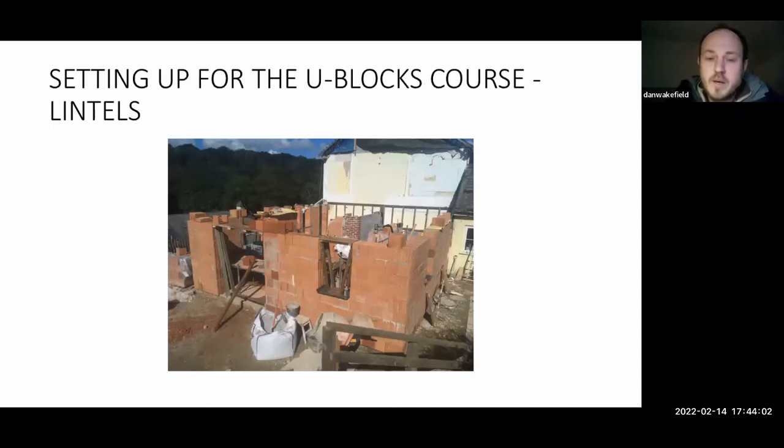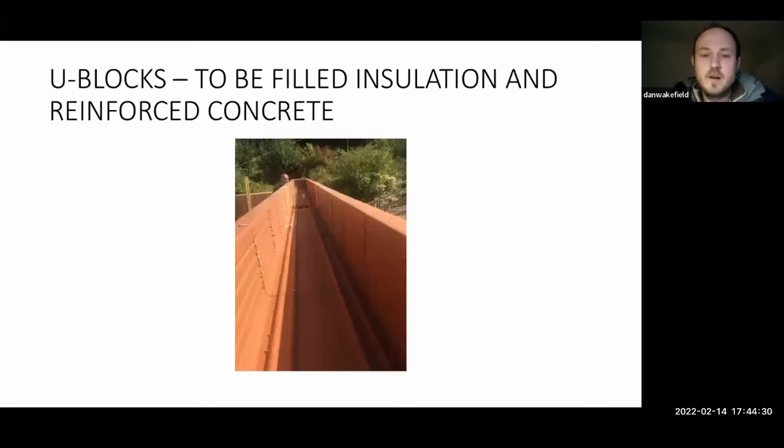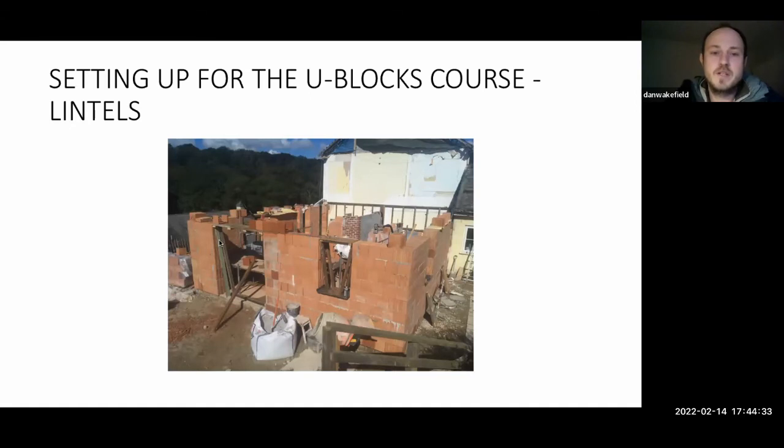Okay, so when you get up to the top of all your lintel courses for your windows, it's obviously much better if you can get all your heights the same. You've got to create a framework for all of them, shuttering out for what we're starting to see here, which is these U blocks being laid on top of the blocks and across all the openings. And I'll just show this here. This is right across the front of this building. Jenny touched on this. We form a concrete lintel right the way across here. So we've got a really strong wall here.